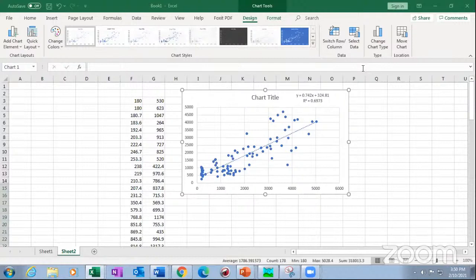Then only your model will be better, because this is a mathematical algorithm. It can give any optimized values, which may not make sense sometimes. So you have to have intuition about those values, and then fix them: if a value is coming within this range, it is the right value, or else you have to change or recalibrate so that the model is logically and practically true for your study area. Sometimes your curve number ends up at 8 or 9. I have seen models where the curve number ends up at 12, 20 also. Those curve numbers are not possible.